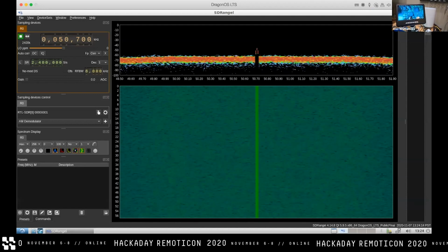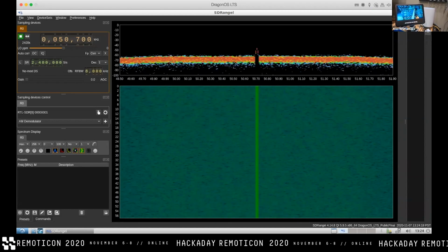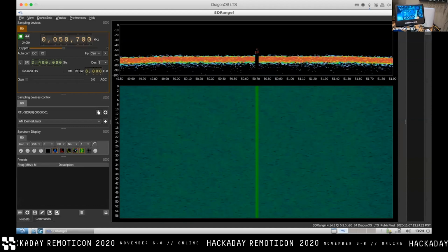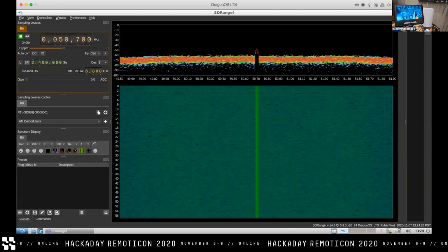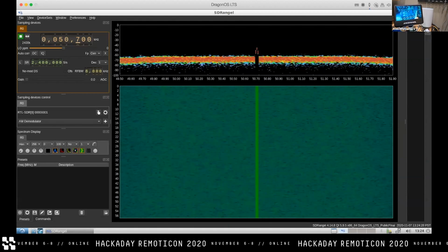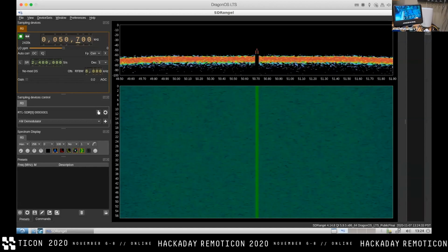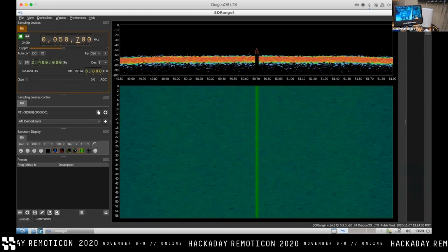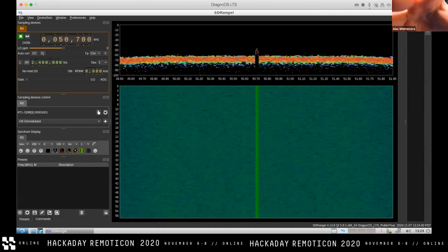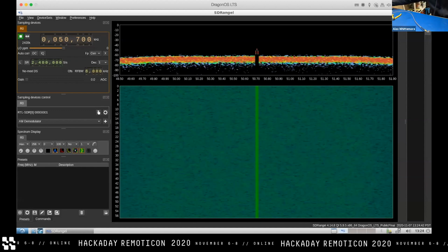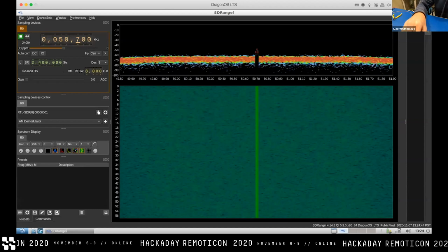The other thing we might notice is this LED comes over here. Oh, I guess I wasn't even probing in the right place. So it makes perfect sense that we didn't actually see much up here when I was trying to test each of these individual traces, and we did see a bunch down here. I never even got over to the proper place to measure, which would have been this trace running down there on the top side of the FPGA. Just for giggles, let's go back and see what that has to say about things, because we should be able to see exactly which pin is sourcing all of that current.